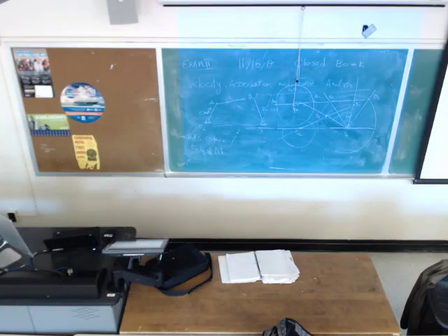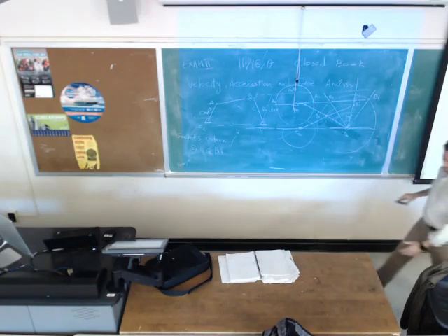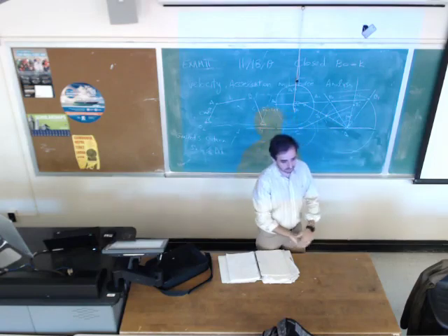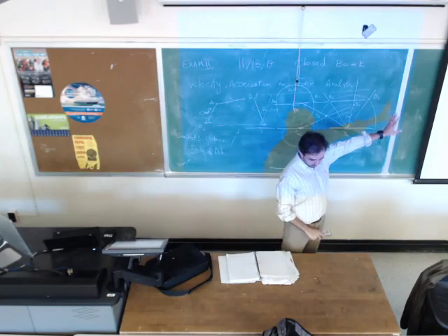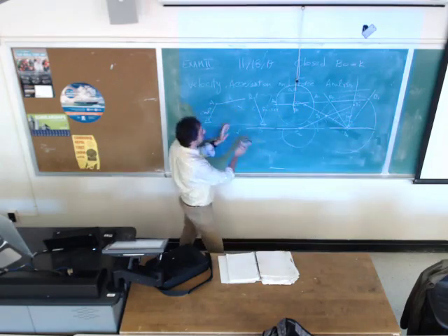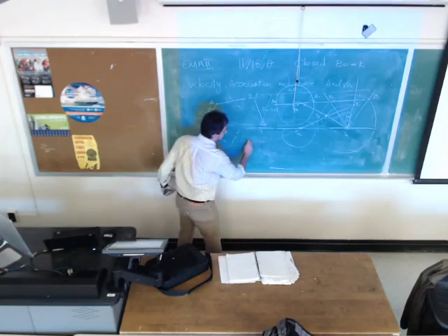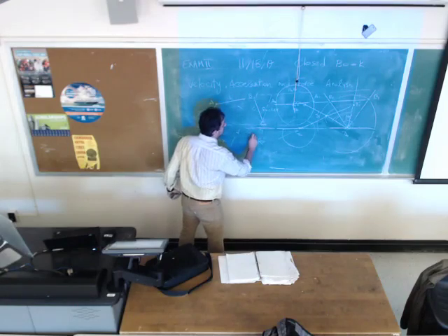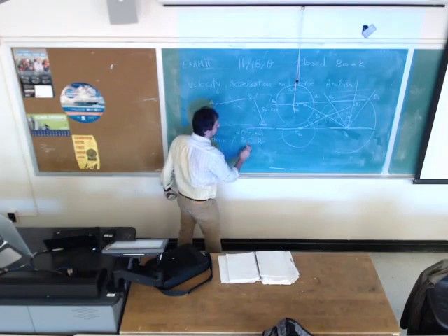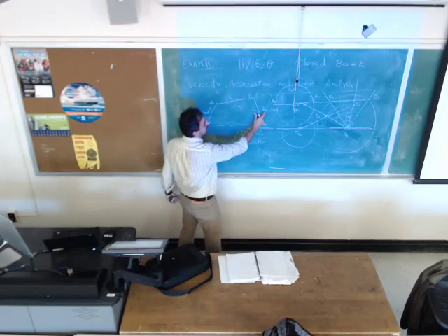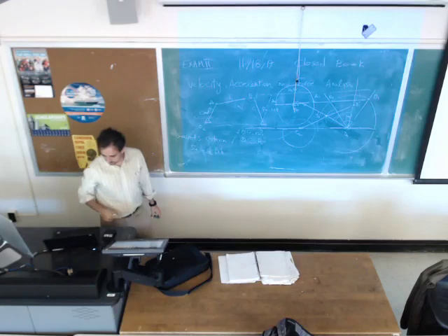It's not going to be identical for everyone. It's going to be different depending on your resources. All we know is what desired motion we want to get out of the mechanism, and based on that, we design. On this problem, yes, I would like to design a crank rocker first. It should be a 4-bar mechanism. It should be a crank rocker, and the rocker should oscillate for 45 degrees. Okay.